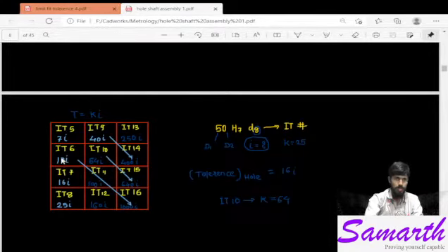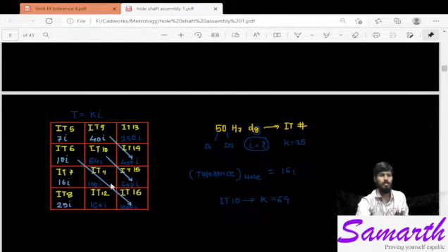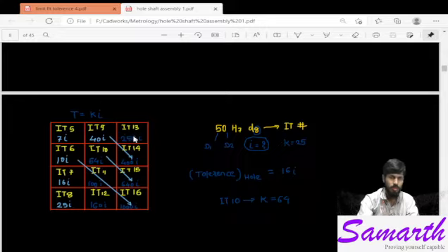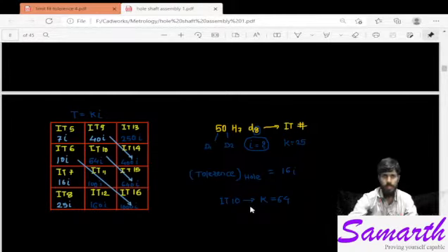If here is 10, here 100, here 1000. Now this is 16 and this is 160. That is 10 times. That means these first five or six values you have to keep in mind. Here this 250 is also taken from this 25, 10 times the 25. So you will get the values of K and the tolerance value T.